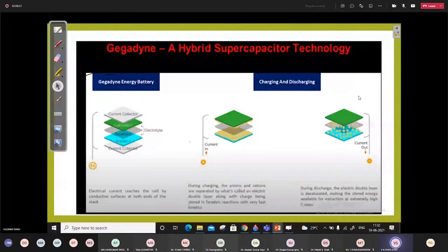And the DC to DC converter can also serve as a battery charging regulator, while a passive hybrid source would require a separate battery charger. So if you have it, then the same can be used to charge the battery. This partially removes the limitation of adding series cells of UC to an upper limit set by the maximum allowable ESR. So it will allow you to use more UC cells in series.